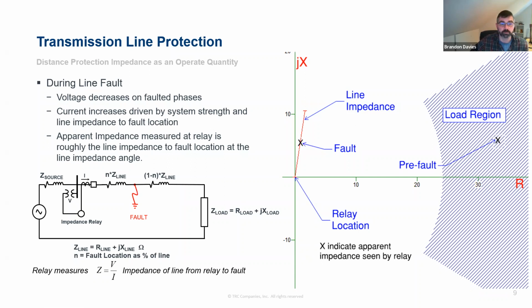Generally, your fault impedance is going to be resistive. That tree is going to have a resistance associated with it. I'm sure it has a reactance associated with it too. I don't know how you calculate that, but it's mostly resistive. An arc is mostly resistive. So what you'd see is this red fault location would have an impedance tied to it that would be mostly resistive.